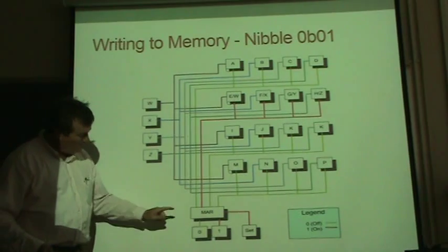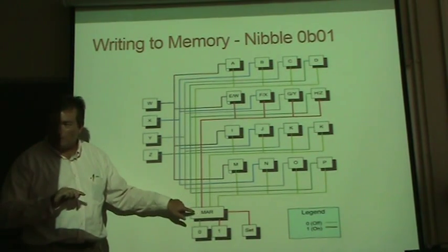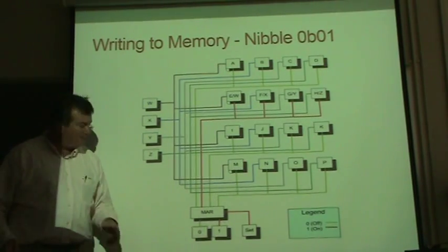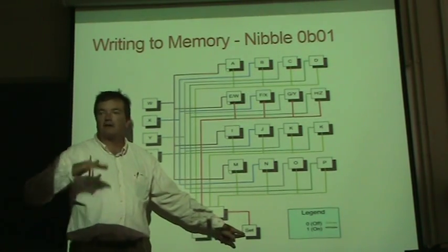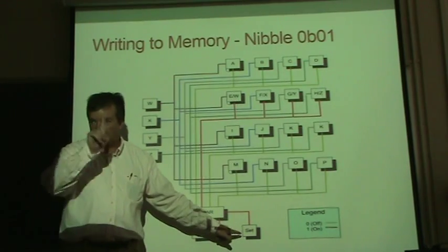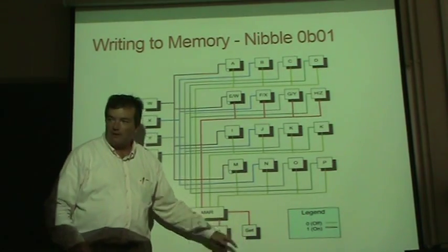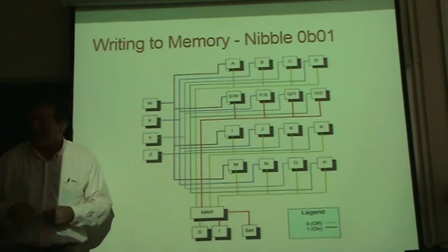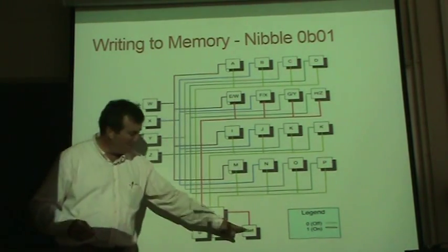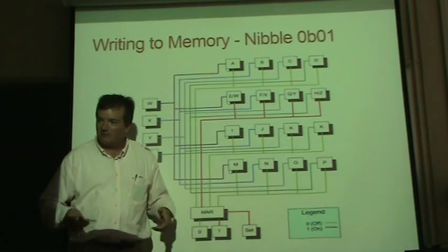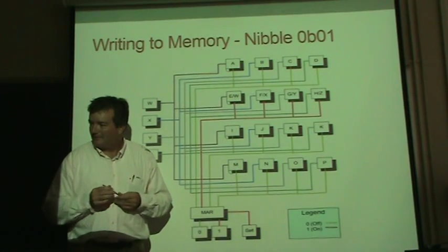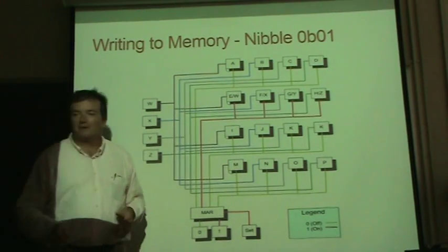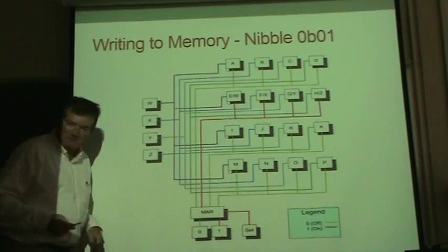So one of the homework assignments is going to be to take a decoder and add an extra bit so that if this bit is on, it acts like a decoder, meaning one line is on. If this bit is off, it shuts off everything. So anyone have an idea what this bit would do with the outputs of the decoder? Okay, well, like I say, that's one of the homework assignments. I was hoping that was one of the easy ones.